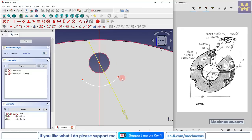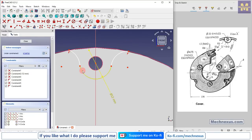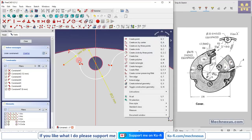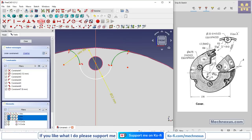And we will move this arc approximately, and we will create an arc. Select a 3-point arc, select this and create an arc on both the sides. And now I will select this and add a tangent, select this and add a tangent, and this is of R6, so we will select radius and provide 6 mm, and select this and add equal.